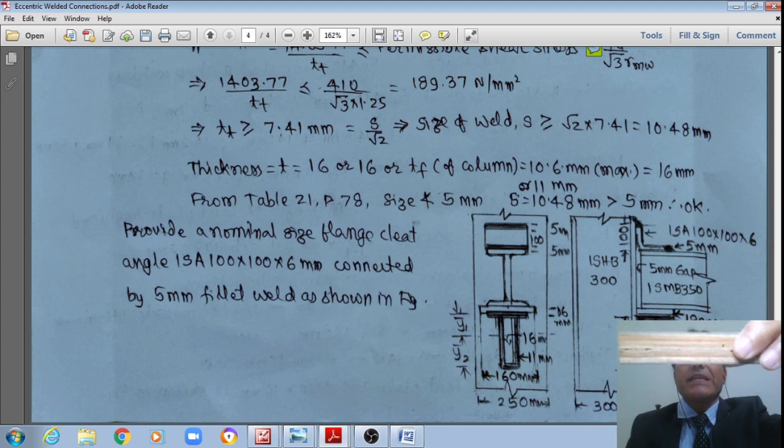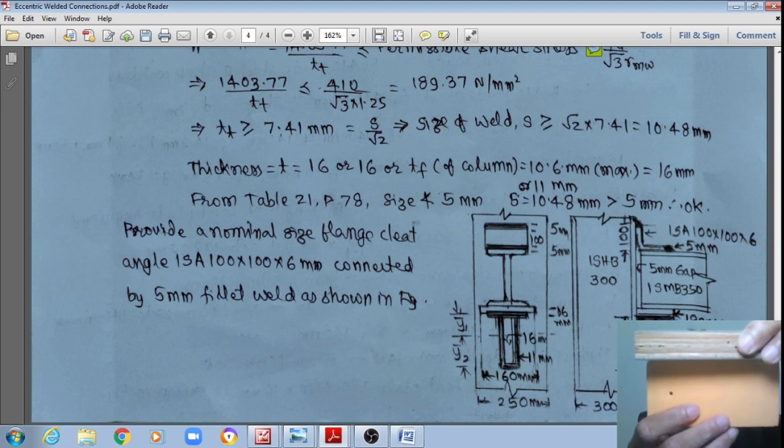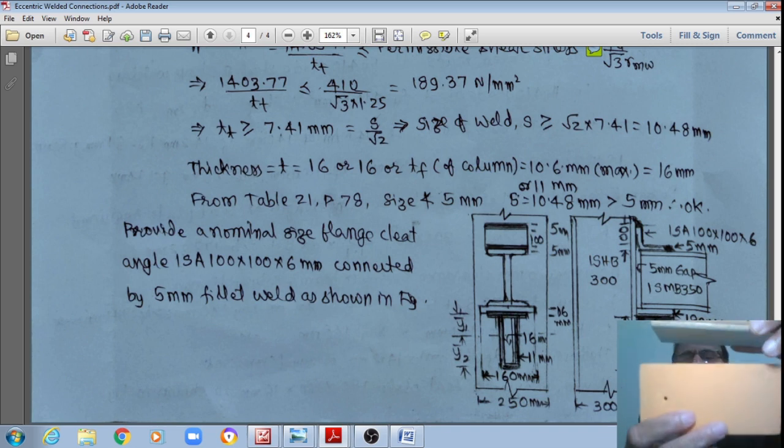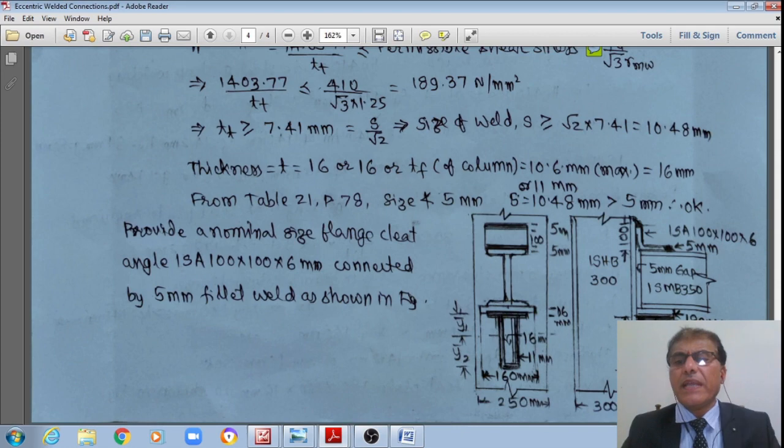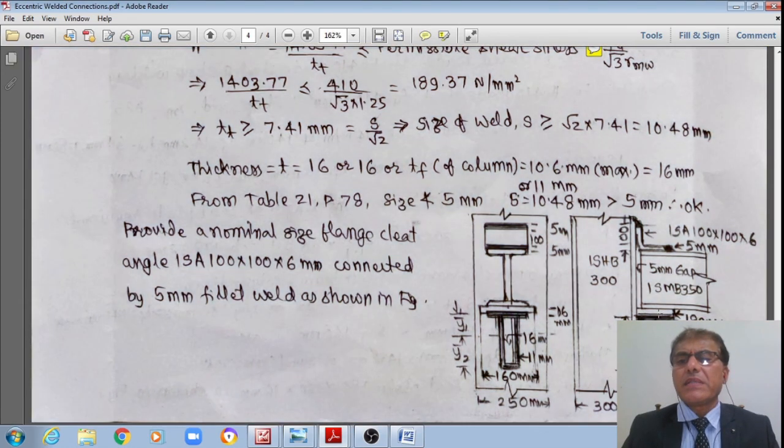Therefore this is how the seat plate width should also be matching with that same value, therefore 180, right? That is how this 180 mm is along the x-axis. Along the y-axis the depth is equal to 300 mm, just now we have designed, and its thickness is equal to 16 mm. This is how the design of the stiffener plate is done. Even now we can see in side view the thickness 16 mm, and its depth is seen as 300 mm, of this stiffener plate, right?